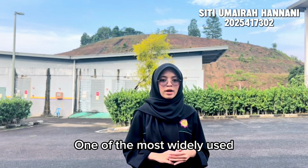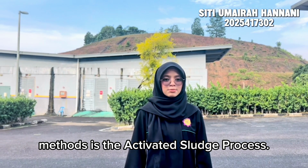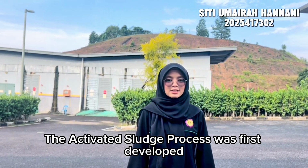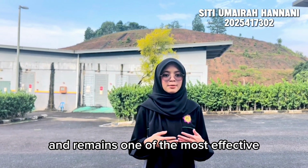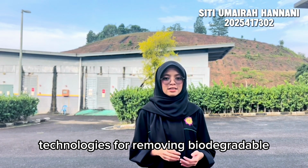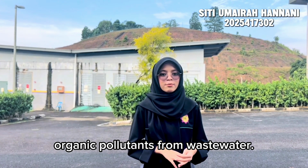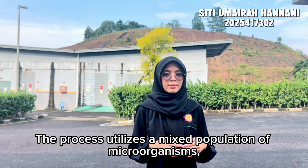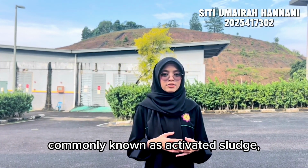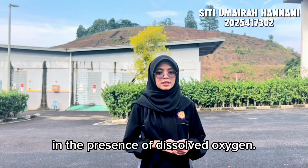One of the most widely used biological wastewater treatment methods is the activated sludge process. The activated sludge process was first developed in the early 20th century and it remains one of the most effective technologies for removing biodegradable organic pollution from wastewater. The process utilizes a mixed population of microorganisms, commonly known as activated sludge, to biologically oxidize organic contaminants in the presence of dissolved oxygen.